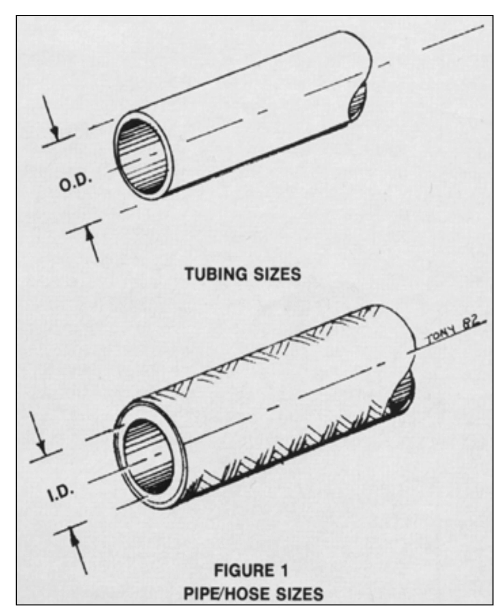What material should be selected for high-pressure rigid fluid lines? Annealed or corrosion-resistant steel. What percentage of flaring is allowed when bending metal tubing? 25% max.